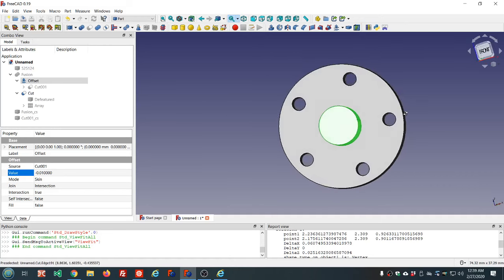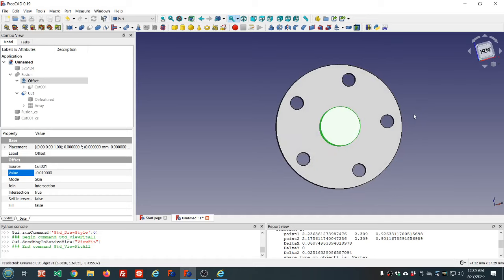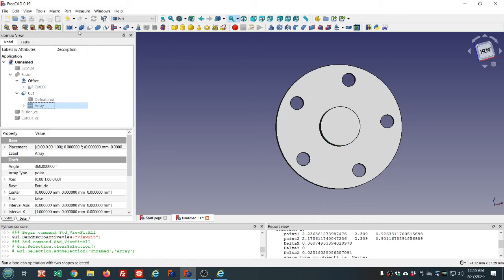But there could be times when you created an object in FreeCAD, and let's say we needed a 5-hole pattern, but we only had 8 holes. In which case we could remove the extra holes with the defeaturing tool. It would be nonparametric, but that would be a way to do it. I would prefer instead to use the explode tool, which we used before here on the array, and do it that way. And let you get at the individual items in the array.